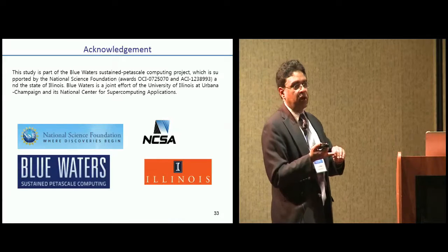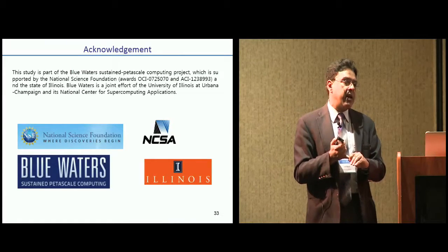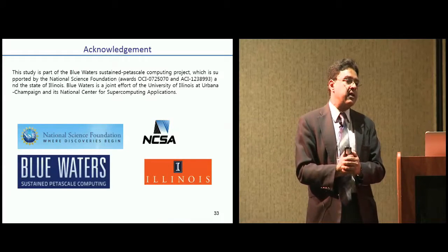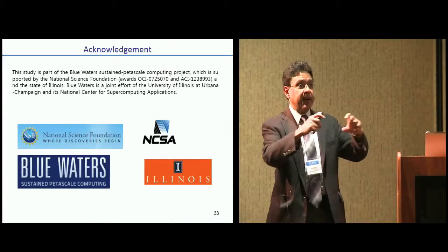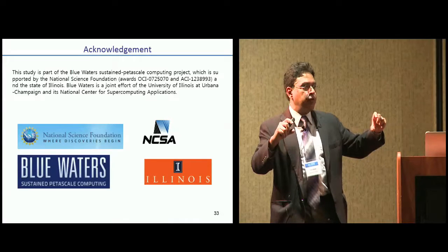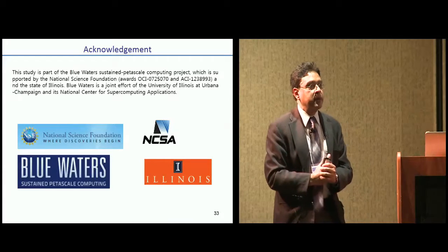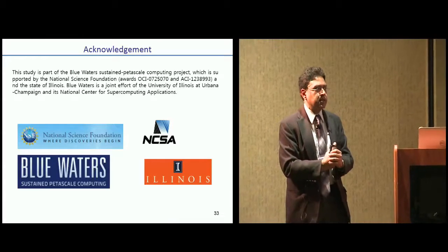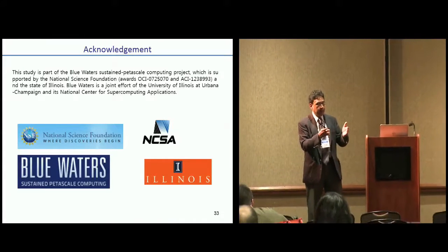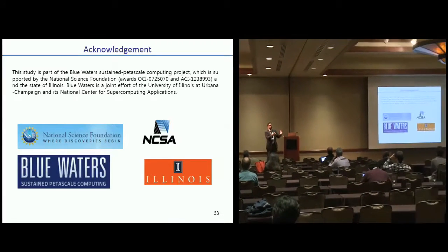So there is what is called mathematical instability. We develop techniques to suppress that, and there are stabilized methods that have been developed to address that. In our case, we have developed these methods based on what is called variational multiscale, which gives you the ability to develop a fine-scale mathematical model and therefore not simply add, for example, an artificial viscosity, which most fluid mechanics models do. Here I could not show you the details, but we have published enough papers on that. The fine scales are in fact proportional to the residual of the Euler-Lagrange equations of the coarse scales.